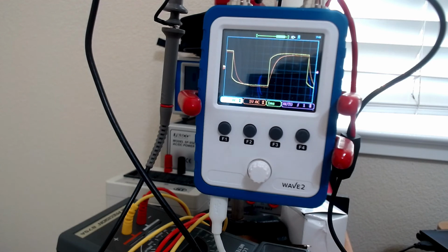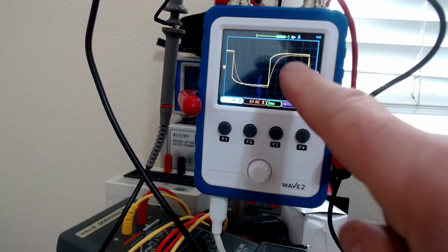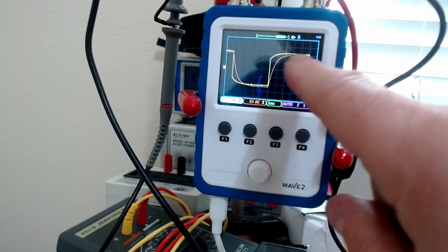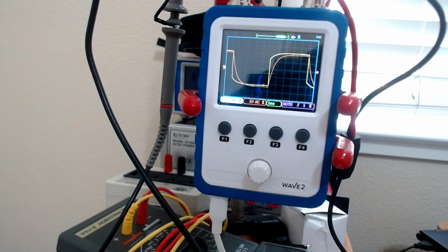I changed the RC time constant by making C smaller, and you see that the capacitor is basically completely charged because you're asymptotically reaching the power supply voltage. If I actually made the time constant bigger, then you would see the capacitor not charge up as much.